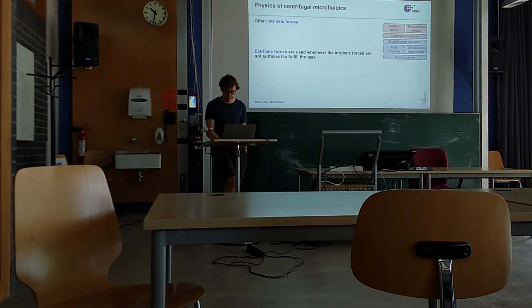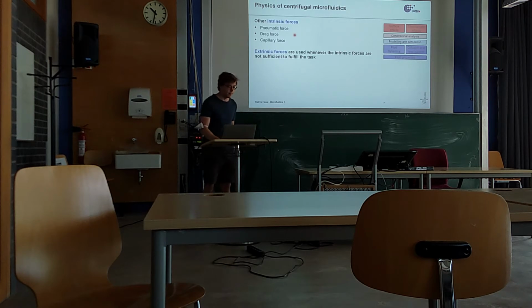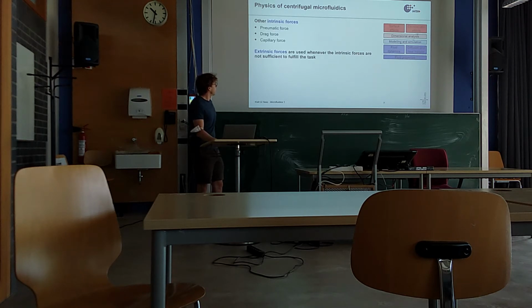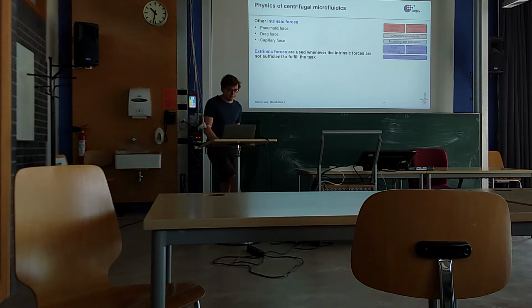One of your colleagues online said viscous and capillary, so the viscous forces we already had, and the capillary forces, obviously they are part of the surface effects lecture, and so those are our three intrinsic forces that exist in centrifugal microfluidics. You can already see that I also highlighted electrokinetic effects.